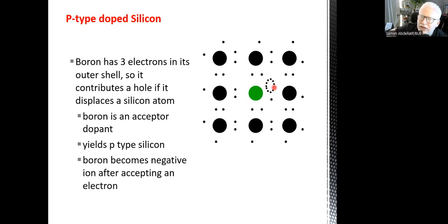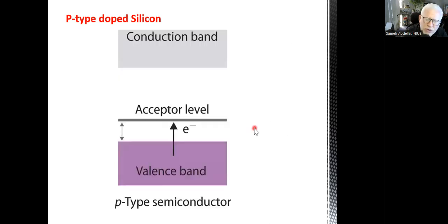or without a corresponding electron. Accordingly, you increase the number of holes without increasing the number of electrons, and then your Fermi level will be shifted downwards in order to have a p-type material, or in other words, a material where the number of holes in the valency band is greater than the number of electrons in the conduction band.